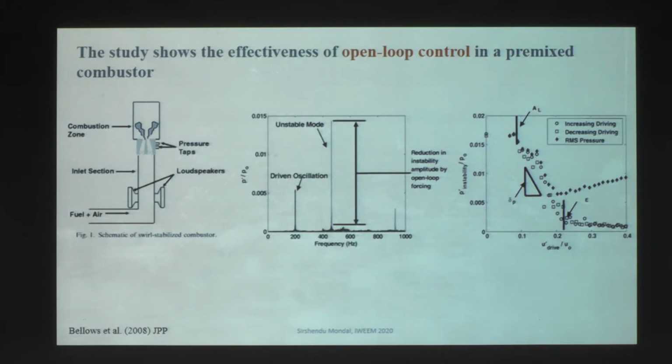So here is the gap. Basically there should be a systematic investigation, a clear picture, of which frequency we should choose for open loop control that will lead to the maximum mitigation of thermoacoustic instability.